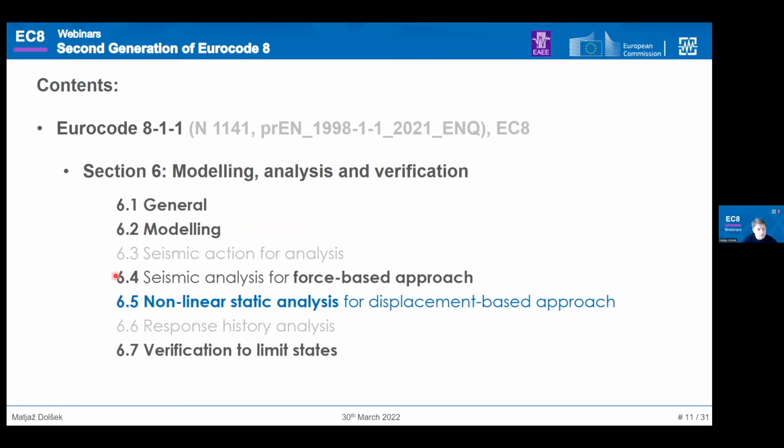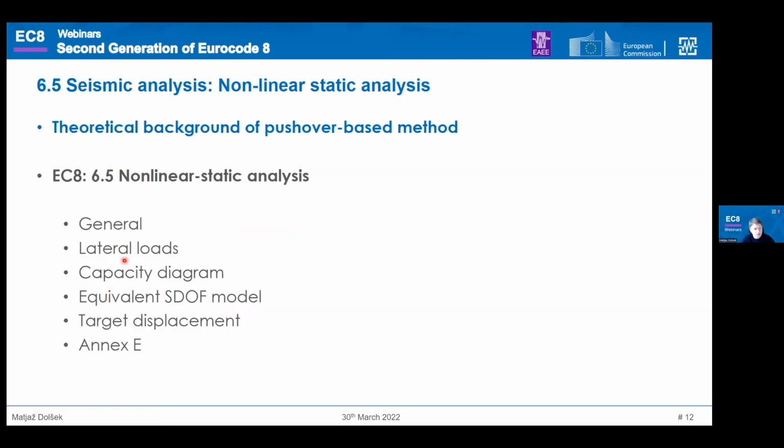Okay, so this is about the 6.4 force-based approach, and then we go to 6.5, nonlinear static analysis. Here I will present a few slides about the theoretical background of this analysis, and then I'll talk about Eurocode 8, section 6.5, which is decomposed into the following parts: general lateral loads, capacity diagram, equivalent single degree of freedom model, and target displacement.